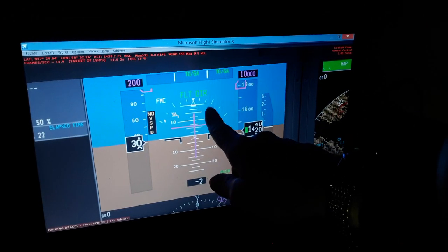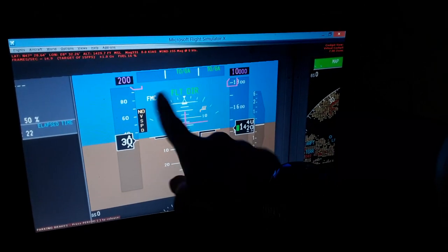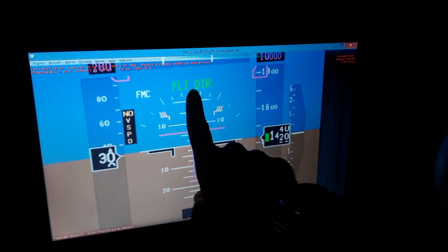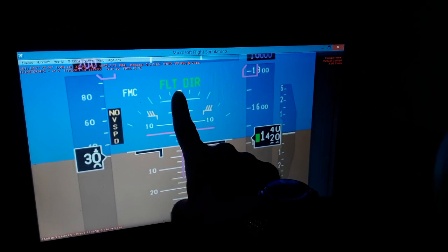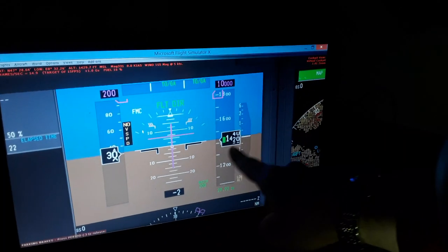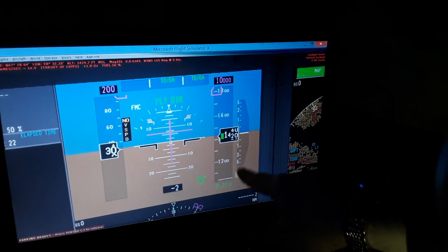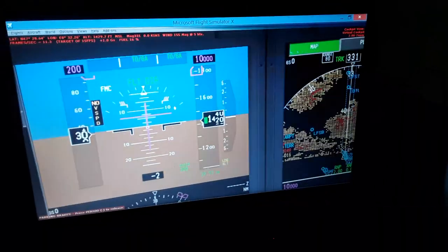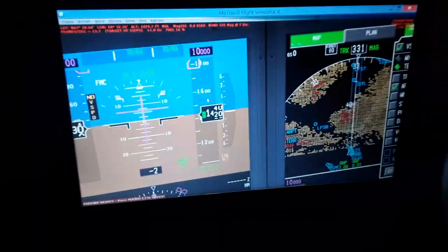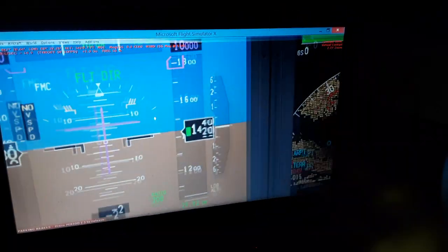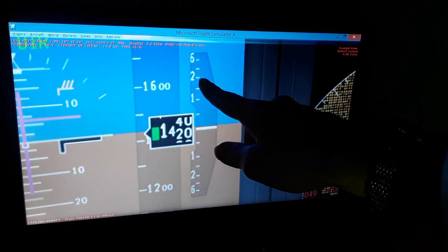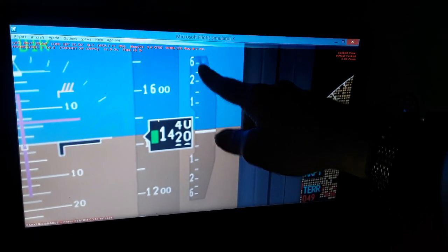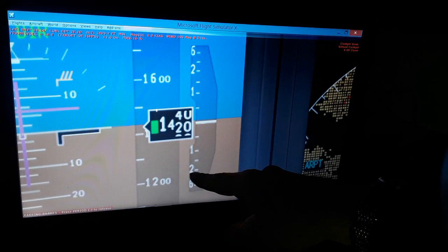So we have the side slip indicator. You can see the turns when we're turning. It shows turns in the air, how many degrees, like 5, 10, 20, 30, 45 degrees, left and right. Also the barometric altitude, the barometric pressure of the outside atmosphere over here. The vertical rate of climb or descent of the aircraft in tens, hundreds and thousands of feet per minute. So you see this needle moving up, 500, 1000, 1500, 2000, 3000, 6000 feet when we climb or when we descend.